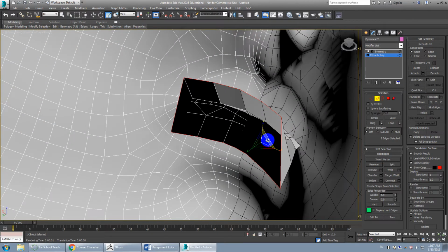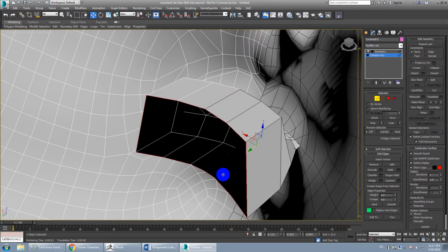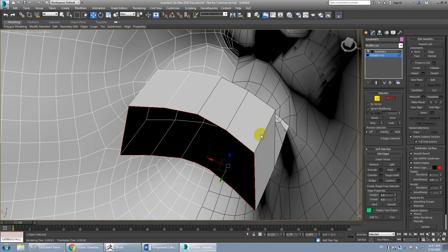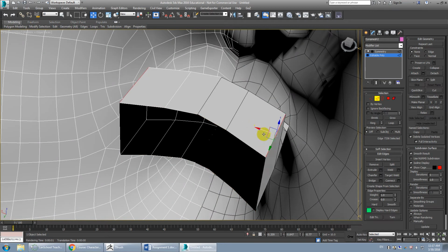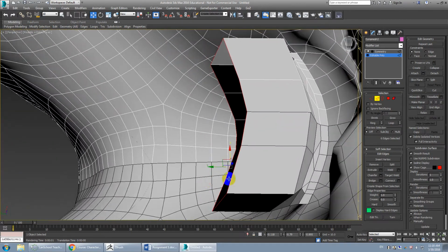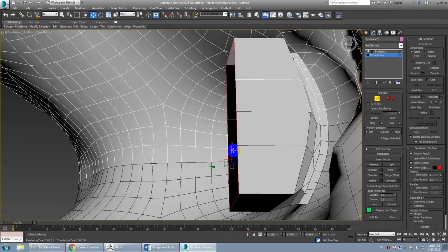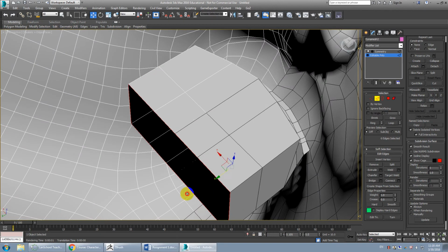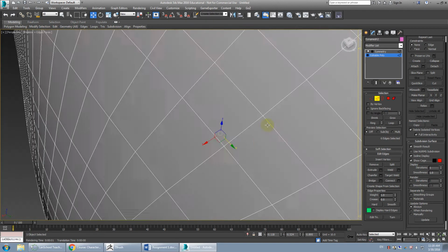And then what you can do is Shift and move back. Again, if you need to change the shape, you can do that quite easily. At this point, just grab an edge, pull it around. And that's one of the benefits of having that simplified cage, is that it's easy now to make this shape. And I can also do, let's say, make planar, I guess, on Y. There we go. Create a nice kind of even shape there. Hold Shift, drag it back again.